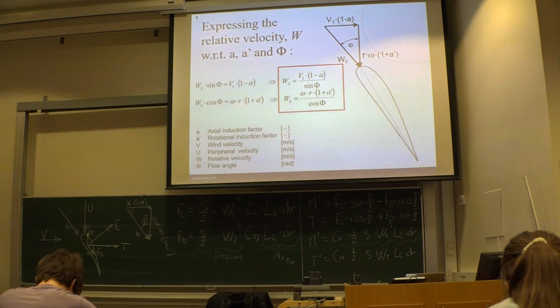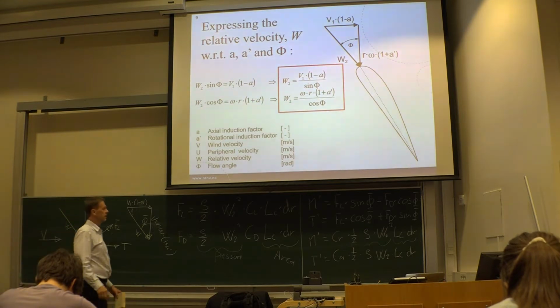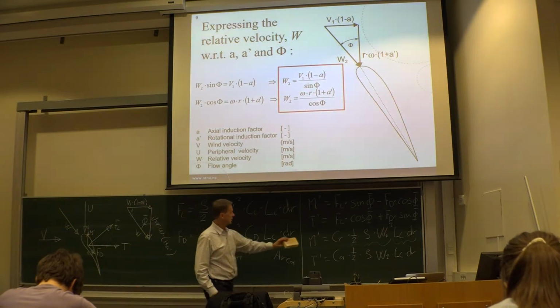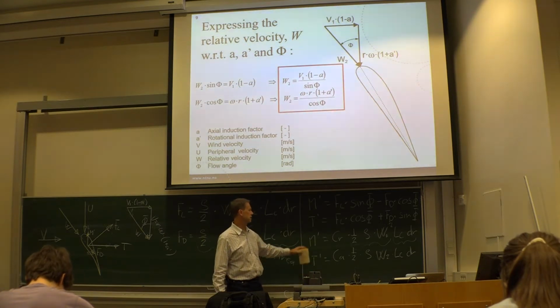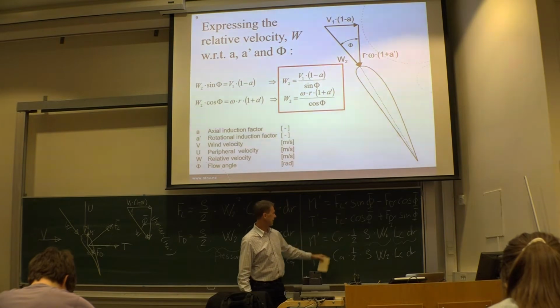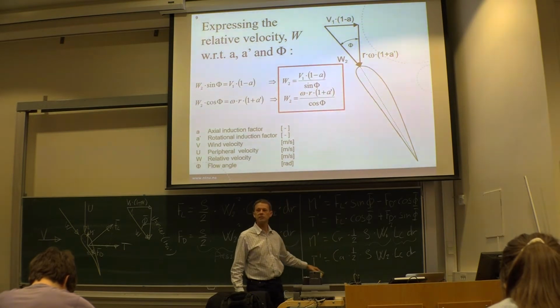We just derived equations for the forces in the rotational direction, or torque direction as you call it, and the thrust direction based on airfoil theory. We ended up with these two equations. We simplified the geometry a little bit and then added CR and CA into the equations.